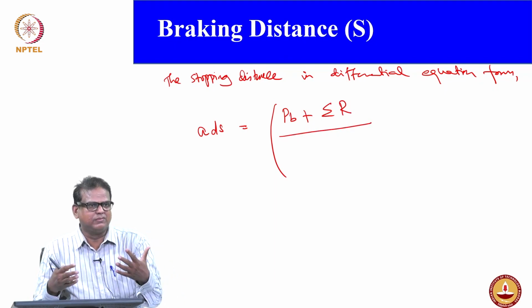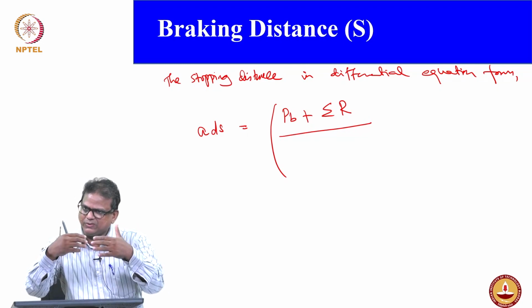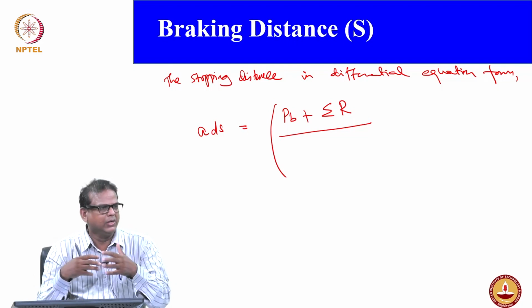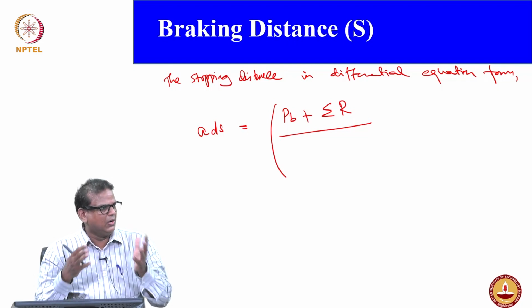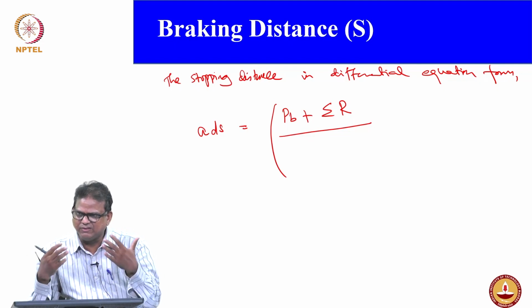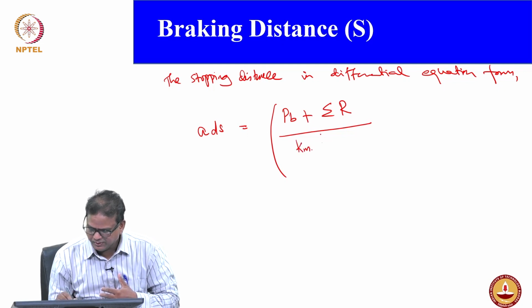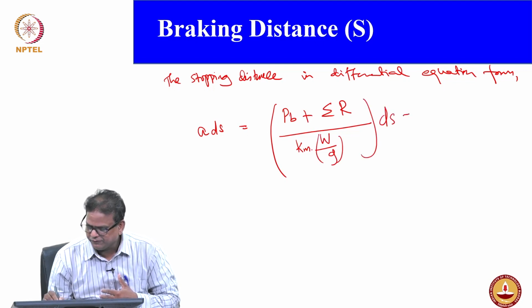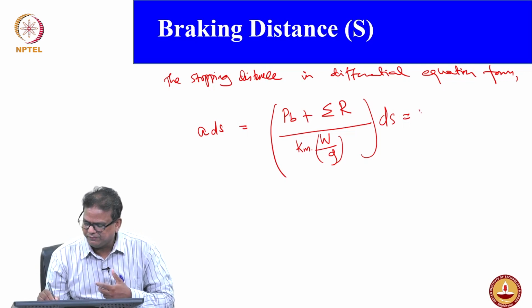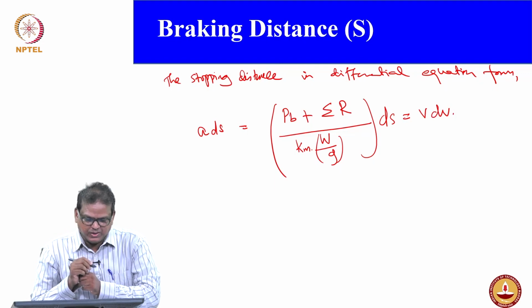When a vehicle moves, you have kinetic energy, but there are certain components, like the clutch, gears, universal joints, all rotating, which will have an inertia effect also. That has to be taken care of. The translating masses give another energy, which you also have to take care of; that is Km W by g into dv, which is the rate of velocity equivalent to your acceleration.